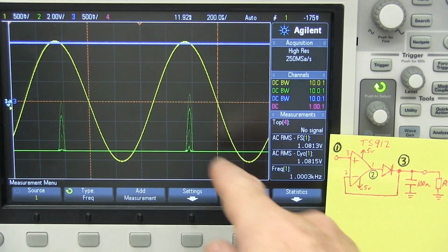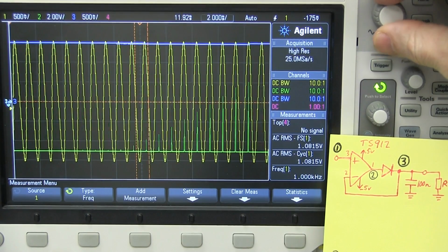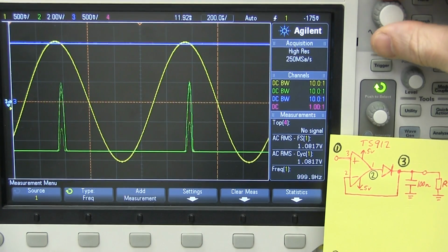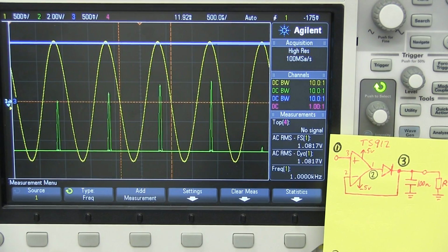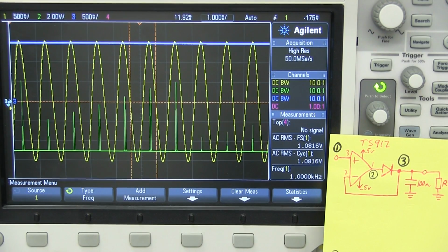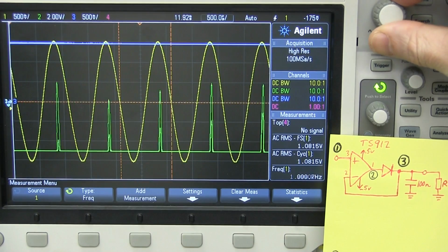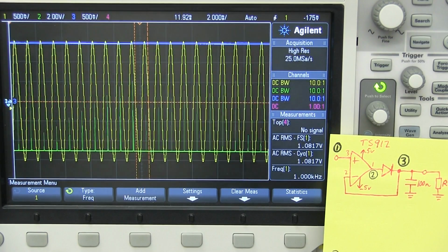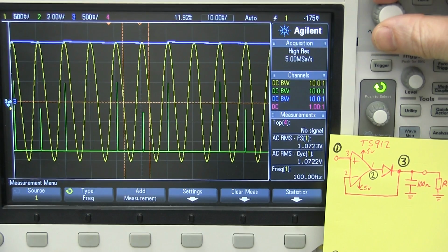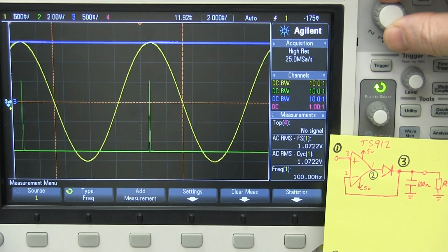So as you can see, there's lots of tricky AC behavior going on in this circuit, and you can really play around and tweak this thing to get exactly the performance you want until the cows come home. I could do a whole 1 or 2 hour video on just choosing the right op amps, different loads, and different types of diodes, and the different values of cap and different values of load, and all sorts of stuff. You can go for hours and hours. There's a lot of traps involved in just a simple peak detector circuit like this. It doesn't always necessarily work exactly as you expect on paper, and over frequency range as well. So just be careful when you're building practical circuits like this. There can be a big difference between the whiteboard theory and what you get in practice.